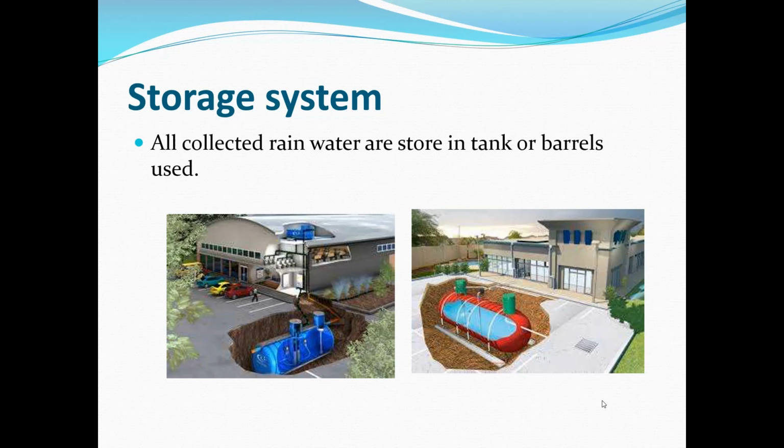Now the storage system. All the collected rainwater is stored in a tank or barrels. Sometimes the recharging of groundwater is also done, if the storage system is quite expensive and we cannot afford it. So recharging is a good option for storage.